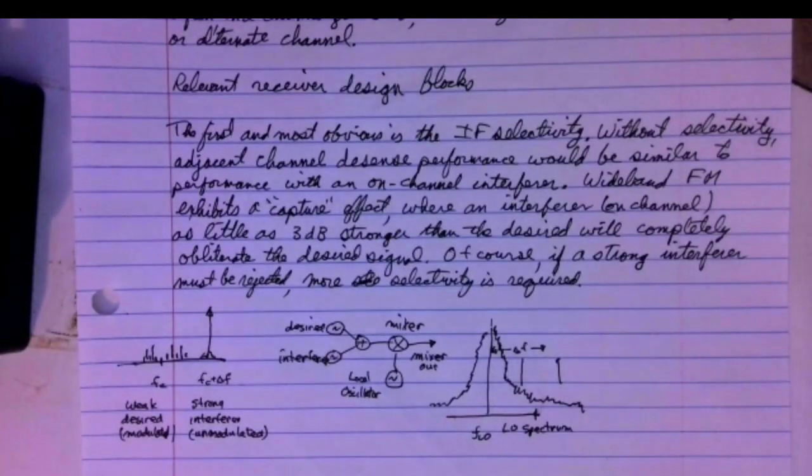I want to mention something about this capture effect. Sometimes capture effect is good. For instance, in FM communications, like for police and fire, you can have skip coming in from other states that completely does not affect the desired communications, because the stronger signal just obliterates it.